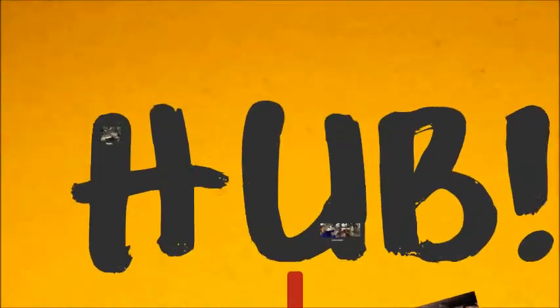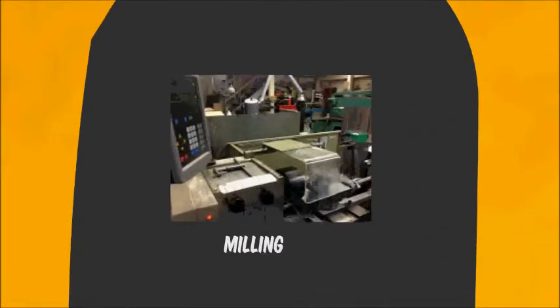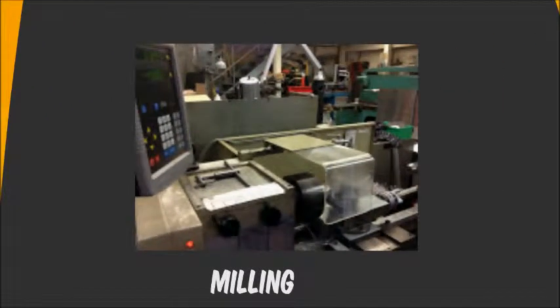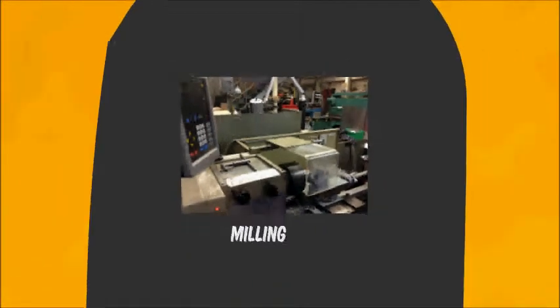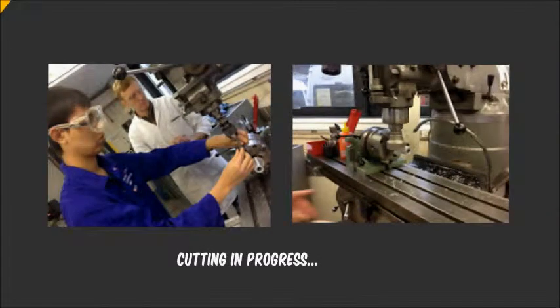Before combining the parts of the turbine blades together, the aluminum hub was to be shaped, which is a key element in between the rotating shaft and cone. The outside of the hub was cut steadily to avoid overheating. This was followed by boring and parting of the hub, in which the processes have to be cooled down by spraying some fluid on the heating surface. After that, the hub was ready to be drilled to allow studding through the center.